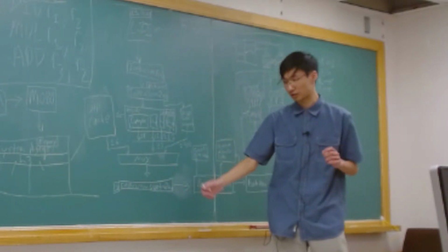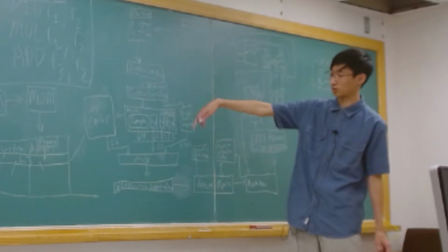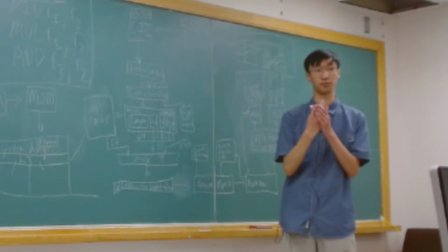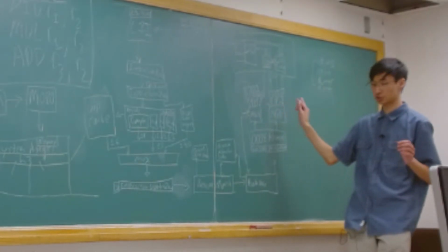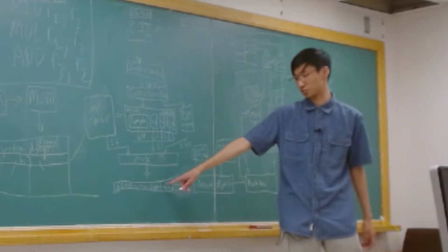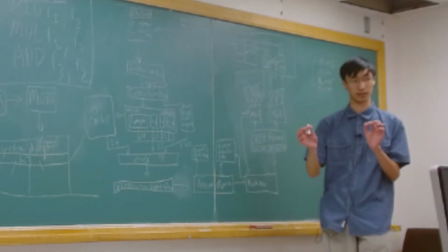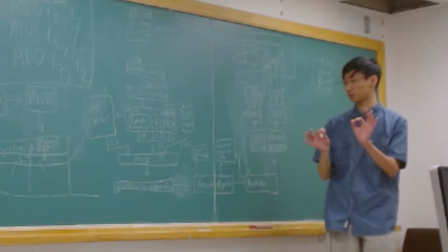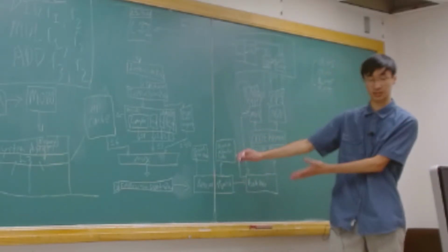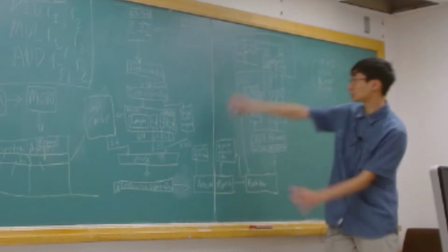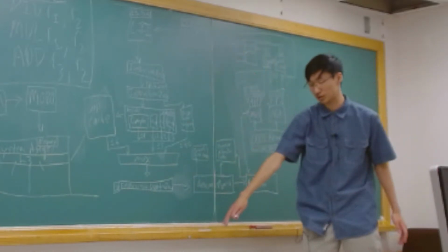We'll do loop stream detection. We'll make sure that our micro operations are fused together so that we can split them apart at math operations or address generation. And then we'll also split them apart at the instruction decode queue or the rename if we need to schedule them completely differently. And then once we go through here, this is the out of order execution area. So this entire section here is known as the back end of the CPU. This is known as the front end of the CPU.